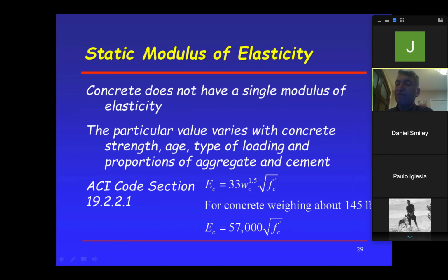But we use 150 because remember, when you put rebars in there, you're going to displace some of this concrete with steel, with reinforcing steel. And the density of steel, and write it down, is 490 pounds per cubic feet. So we take the same box of the basketball, we melt a steel and fill it with melted steel.